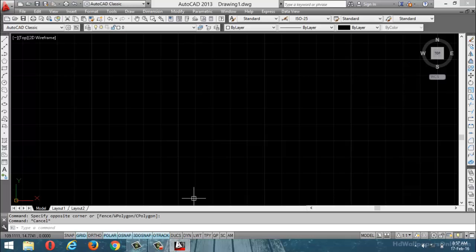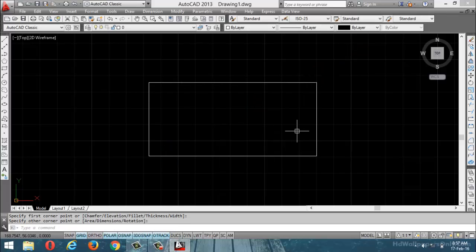Now I am going to design one rectangle with elevation. First, what are my current settings here? What is my current mode? Rectangle mode is fillet and width. First I am going to assign the values 0, and this one also 0. Then I am going to select the internal command elevation, specify the elevation 100, select the first corner point, select the second corner point.